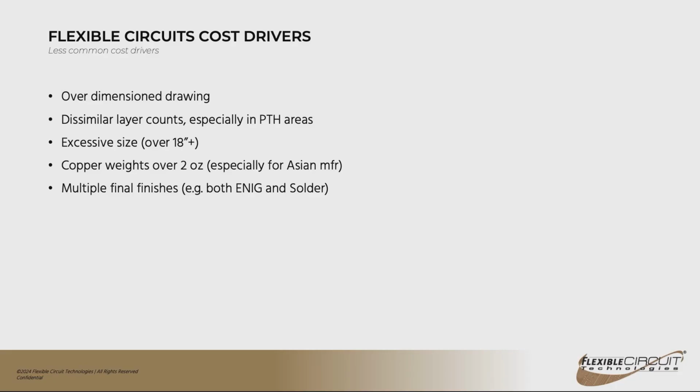There's a number of different ways. Again, pretty much any connector that you can put onto a rigid PCB, you can also put onto a flex. Again, you're going to want to make sure that you have mechanical support for those connectors because those can be high strain areas, and you want to make sure that you don't damage your circuit when it's moved around.